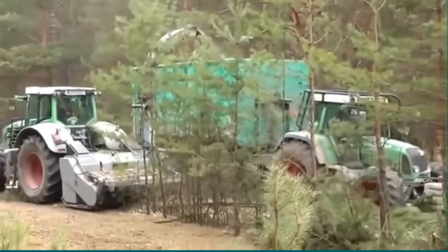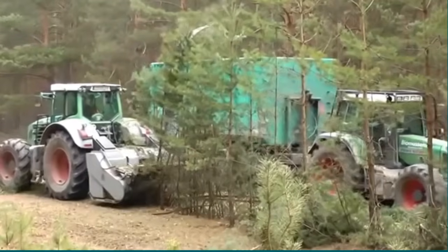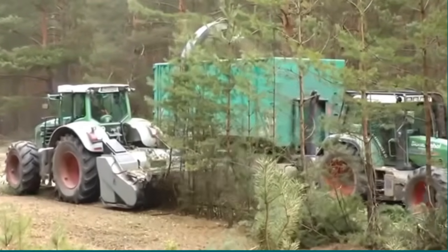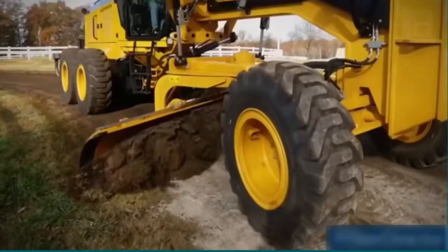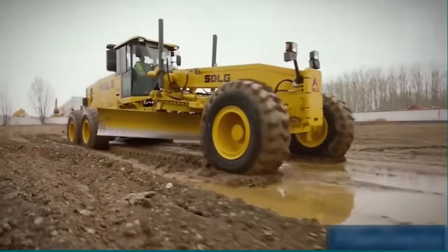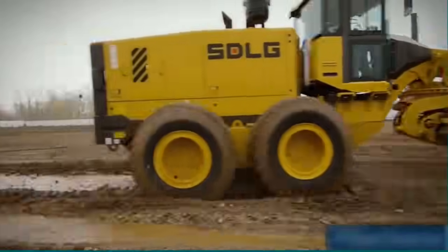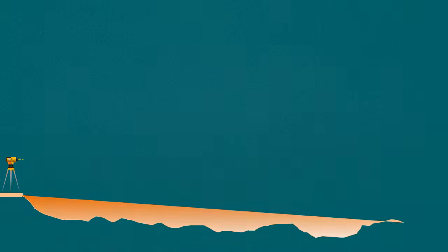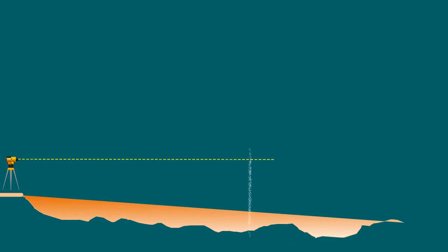This process involves the removal of all surface vegetation along with the root zone and any topsoil. Most projects will involve some degree of digging down to a formation level. There are two common reasons for digging: to accommodate the finished levels of paving work and to remove bad ground, soft spots or other deleterious material. After completion of site cleaning, the top surface of the cleaned existing ground shall be compacted roughly, and again, the reduced level shall be taken for record, before start filling the subgrade, to calculate the quantity of embankment filling required. The method of calculation of the earthwork quantity will be discussed in next episode.